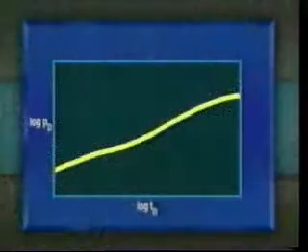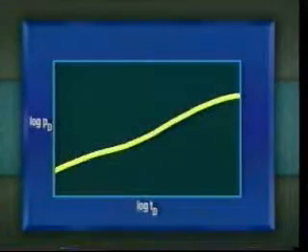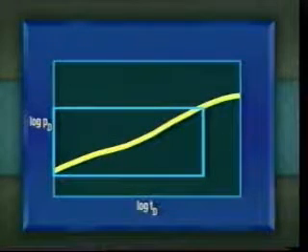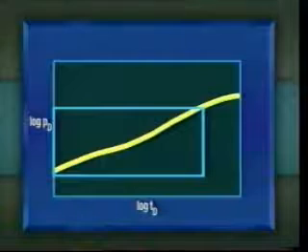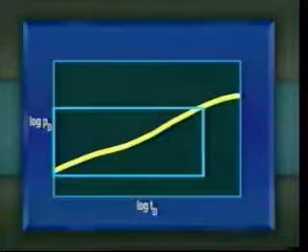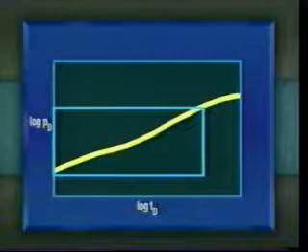If wellbore storage effects last for a significant period of time, it is possible that the first 3 flow regimes will be obscured by its effects. If this occurs, there is no remedy. Analysis by conventional methods to determine fracture length is impossible.